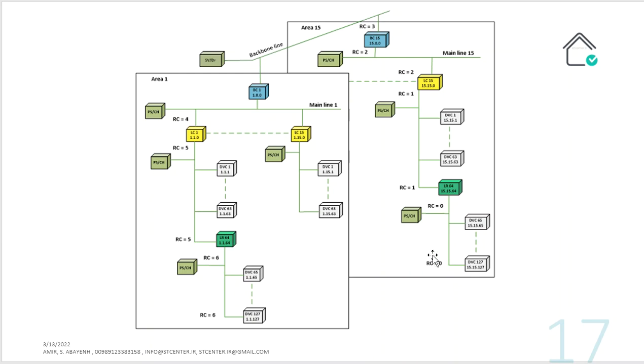So if you connected two lines in a wrong way, for example you make a loop not deliberately, not on purpose, but by mistake, because the routing counter after one loop is going to be 0, the telegram is banned and blocked. So this feature of KNX can help us not to have a very worst case. Yes, great.